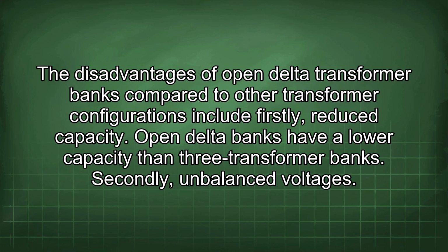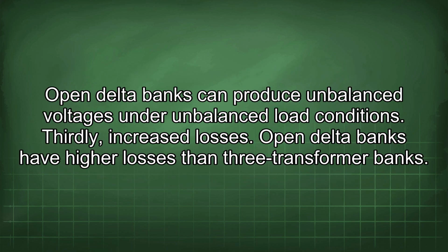Secondly, unbalanced voltages. Open delta banks can produce unbalanced voltages under unbalanced load conditions. Thirdly, increased losses. Open delta banks have higher losses than 3-transformer banks.